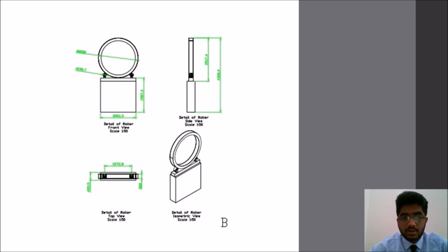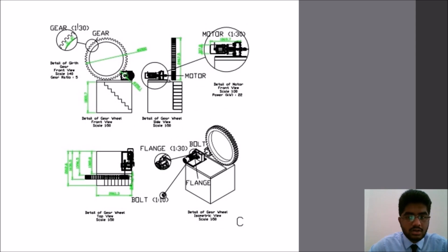Alright, this will be our rolling system, which comprises the riding ring and trunnion wheels. The riding ring is a part of the support structure for the drum and provides a place for pressure to be absorbed, while the trunnion wheels serve as the cradle for the rotating drum, helping to ensure smooth and concentric rotation. This will be our drive assembly, which comprises a motor, gearbox, and gear and pinion. Our gear ratio will be 1 to 5.